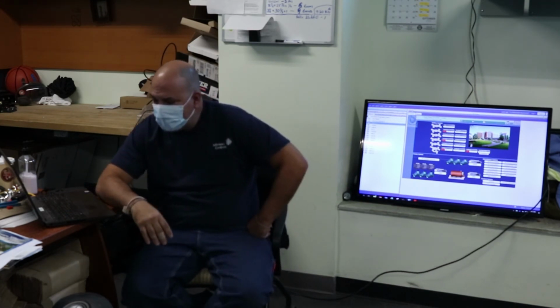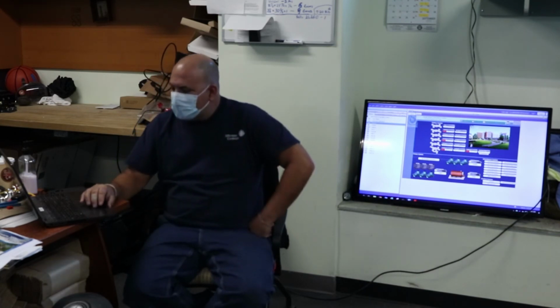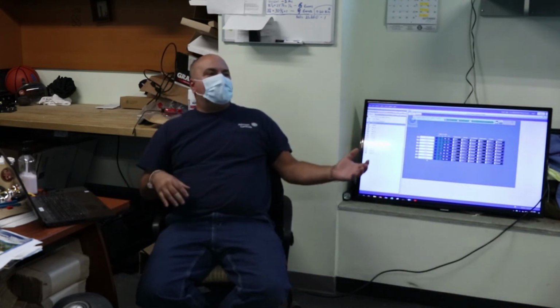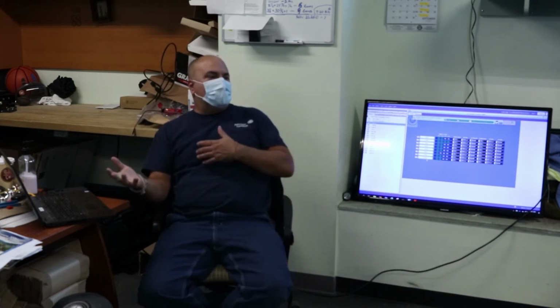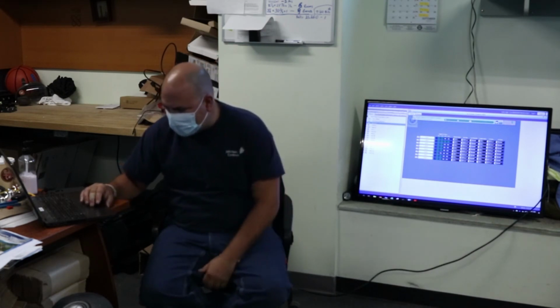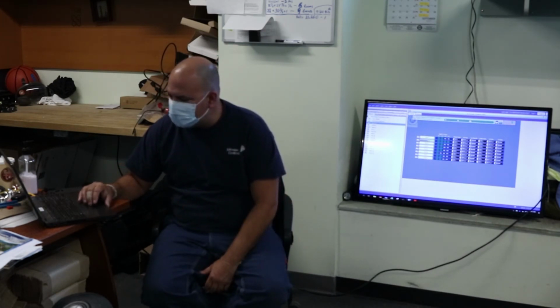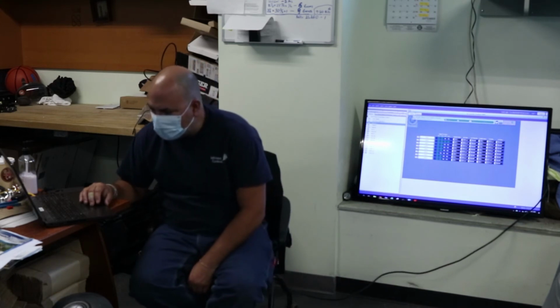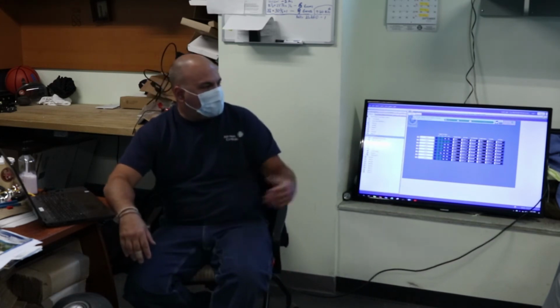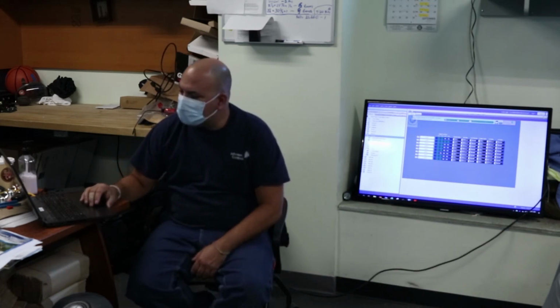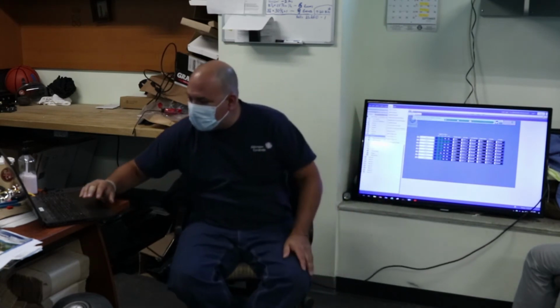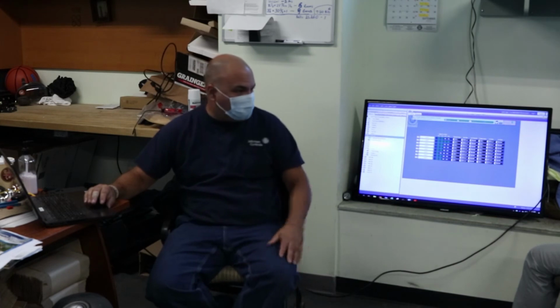All right, I know I showed you guys this last time, but every VAV box that is associated to a certain air handler is in the same NAE. So if we know AHU1 is NAE5, and I wanted to see all the zone temperatures associated with that air handler, what I could do is generate a report. I would go to query up here, but first I'm going to highlight the NAE that I want to see.